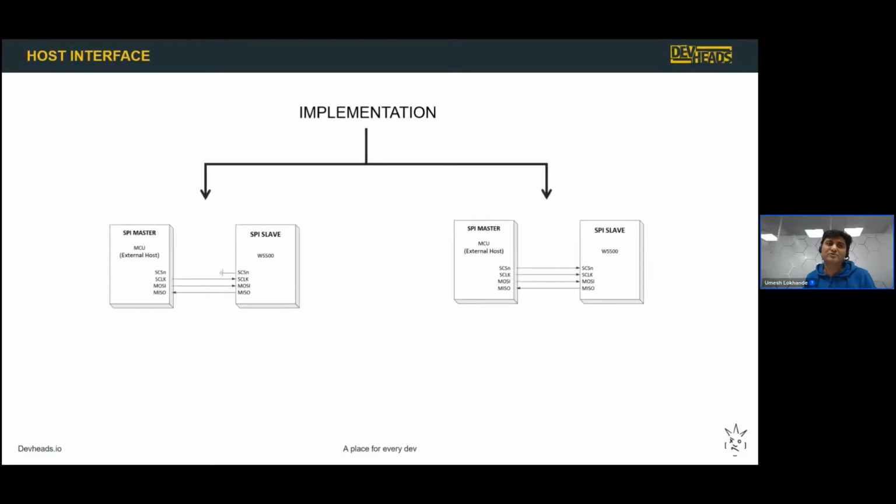Now let's talk about two ways through which this W5500 module will talk to any microcontroller. The first one you can see on the left side, we have this CS line on the W5500 module, and that is connected to ground. So the CS is tied to ground forever. And this version is called fixed length data mode. And what you can see here is a microcontroller. The microcontroller could be anything. We'll take an STM32 microcontroller,